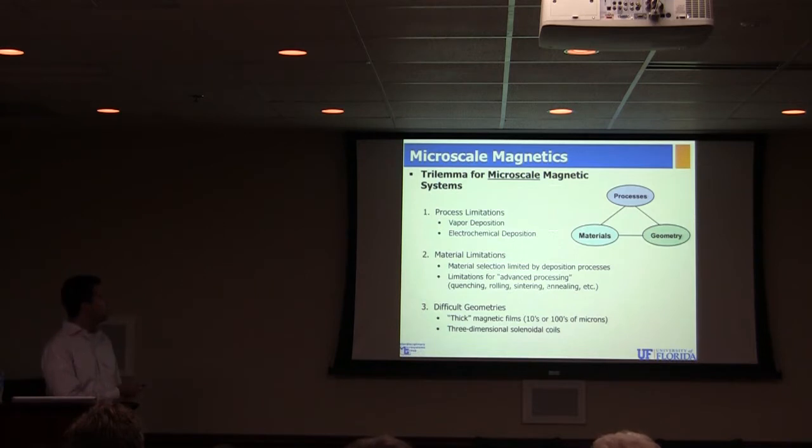And really, the big problem is getting good magnetic properties at bulk. The way they make macroscale magnets, there's all sorts of fancy metallurgical tricks they do. They cold quench the materials, they hot roll them, they deform them, and they do different things to create micro and nanostructure features in the material itself, which give rise to the desirable magnetic properties. We can't do all that fancy business that easily in a traditional wafer semiconductor platform.